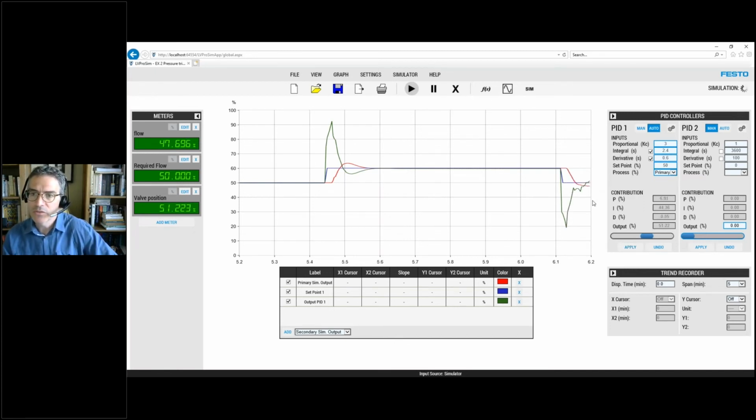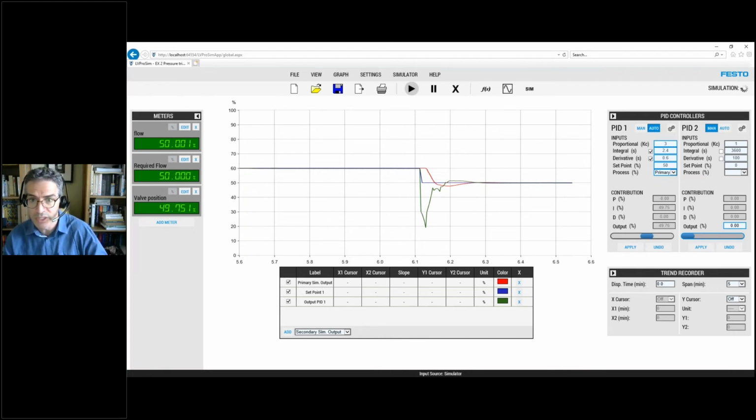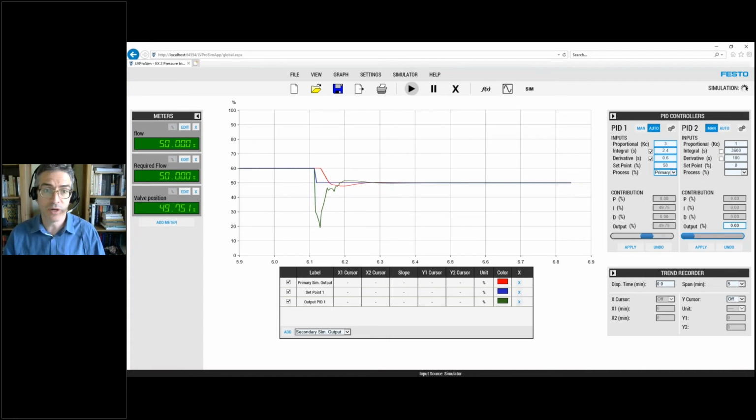You see that the response of the controller becomes really erratic. When the derivative parameter becomes too high, the signals we are sending to the pump become really erratic, and this can be really tiring for the pump, because it will receive signals that tell it to speed up and slow down. So you will hear the pump doing that. This can have a negative impact on the pump in the long term, so you don't want too high a derivative parameter for this reason. So this is the trial and error method and how to find our P, I and D parameters using it.